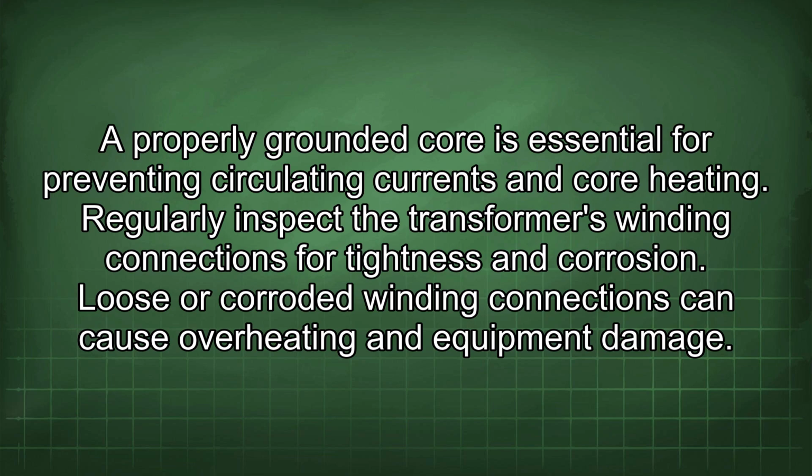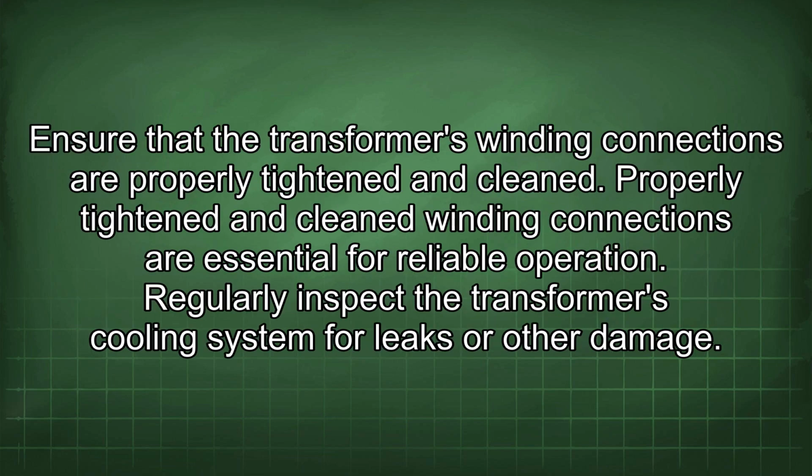Regularly inspect the transformer's winding connections for tightness and corrosion. Loose or corroded winding connections can cause overheating and equipment damage. Ensure that the transformer's winding connections are properly tightened and cleaned. Properly tightened and cleaned winding connections are essential for reliable operation.